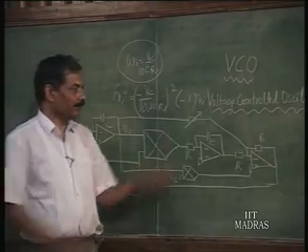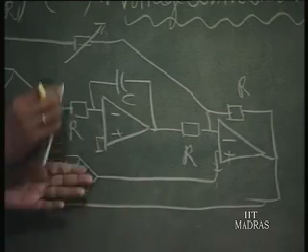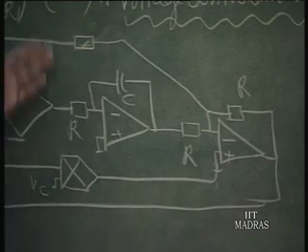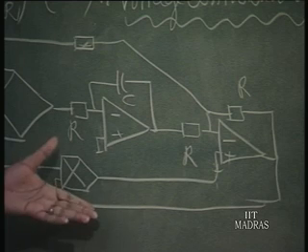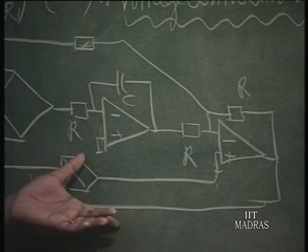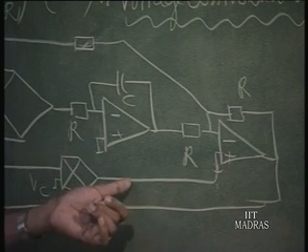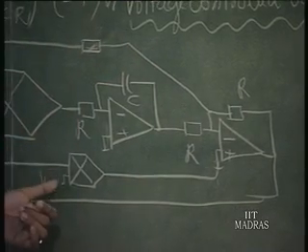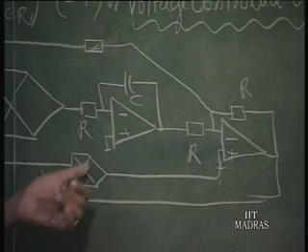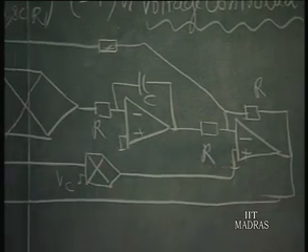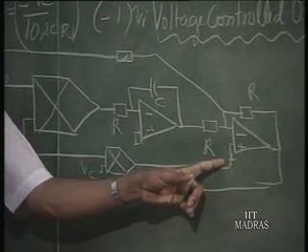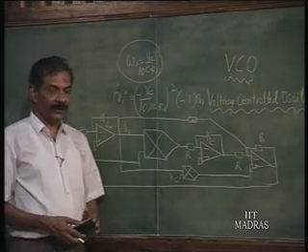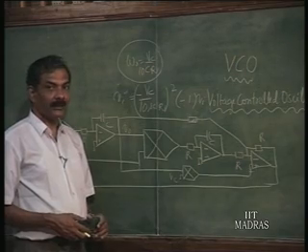So this gives you negative feedback here, this one, this has given you fixed positive feedback. So that initially this positive feedback only dominates, there is no negative feedback here. So the control voltage is 0, that means this output is 0 and only positive feedback exists, and then this output builds up, VC becomes positive and some portion of this is fed back here, so that the negative feedback comes into picture. So this is a voltage controlled oscillator with amplitude stabilization scheme possible.